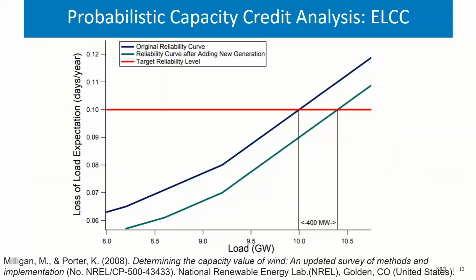However, with probabilistic-based methods, you're using the reliability metrics that I mentioned: the LOLE, the EUE, and the NAUE. With the probabilistic methods, you're taking more things into consideration, and I'll go over that when I start talking about PRAS. However, I just want to give you a high-level view of two of the commonly used methods.